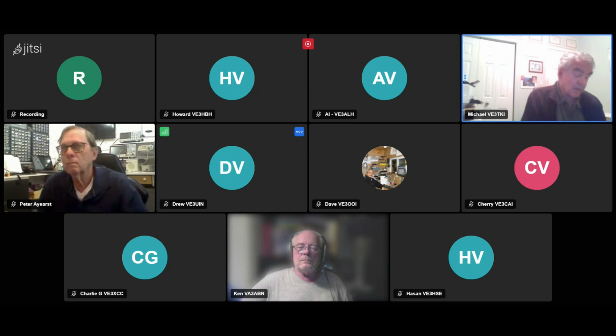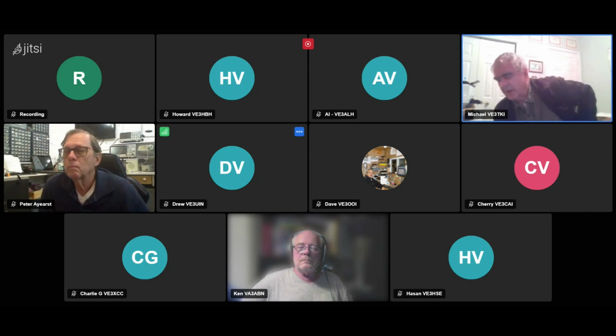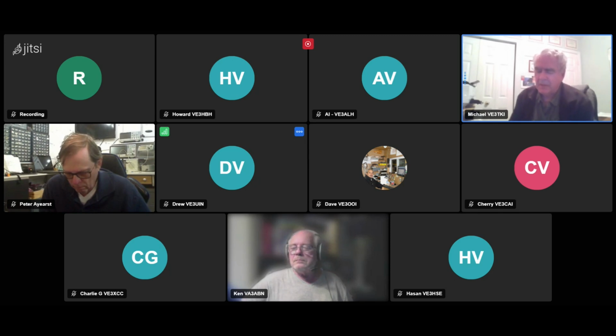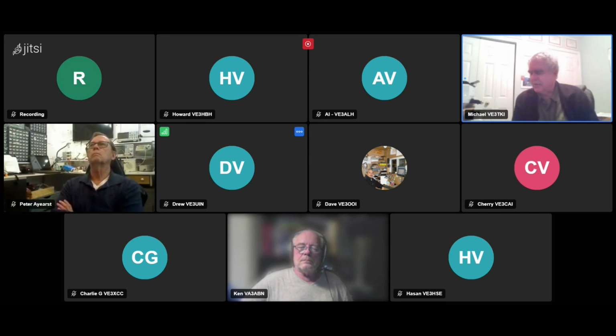As far as the backplane, Charlie particularly has done a lot of work in figuring out how the backplane should be laid out, different options as to numbers of traces and whatnot, and how big the backplane has to be. The JLC PCB size is 100 by 100 millimeters. It's possible to go bigger, maybe without a hugely extra expense, so there's some work to be done to figure that out.